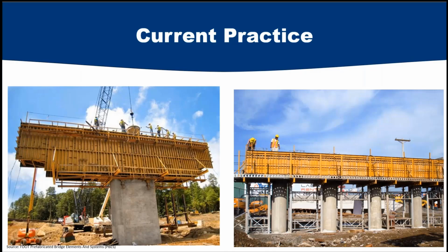You can put a lightweight concrete inside, because remember, the rapid chloride permeability numbers are very low for UHPC. So what's inside is going to be protected probably for life. And even that small thickness of a UHPC shell that you provide adds quite significantly to the strength of the element.